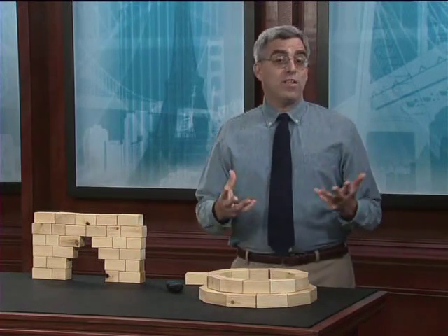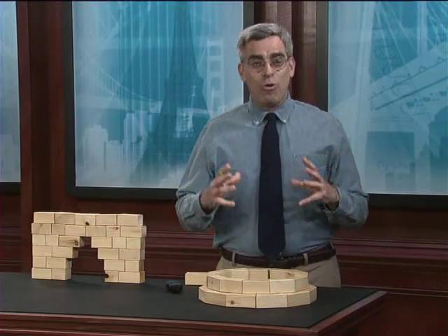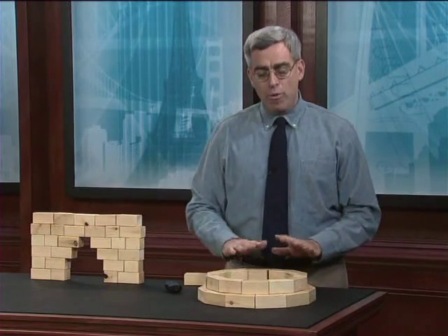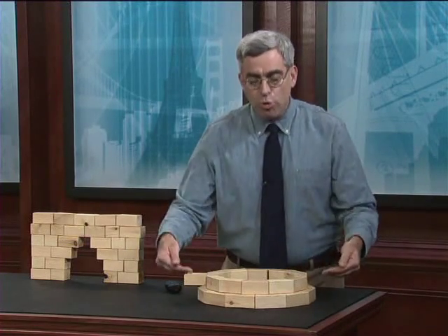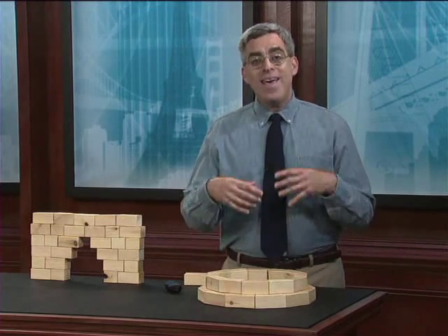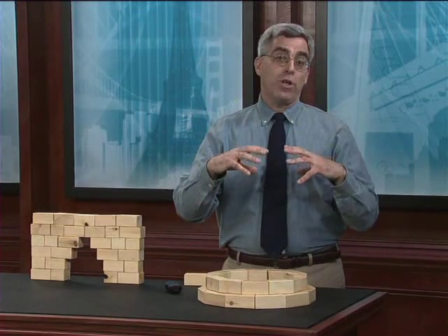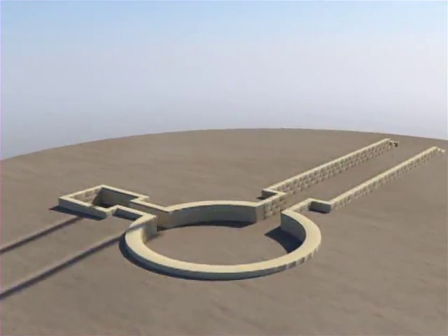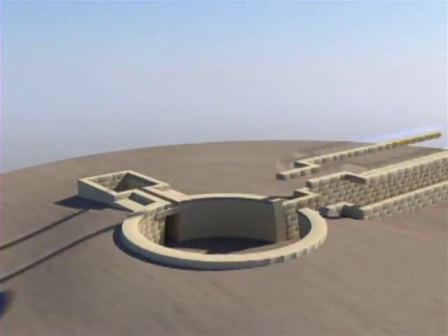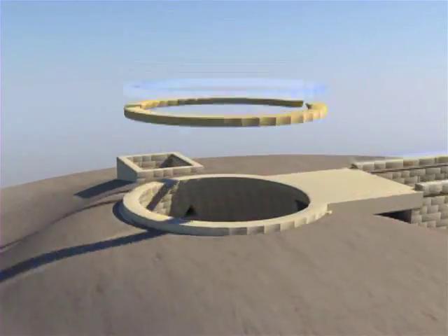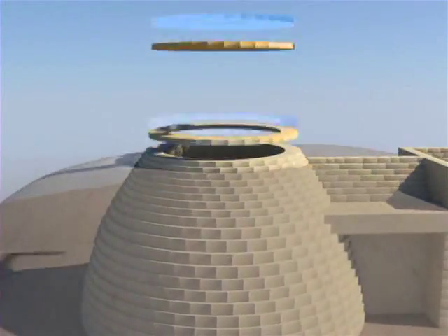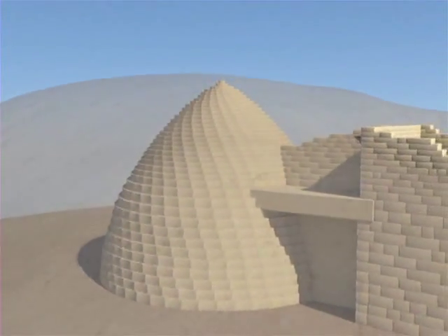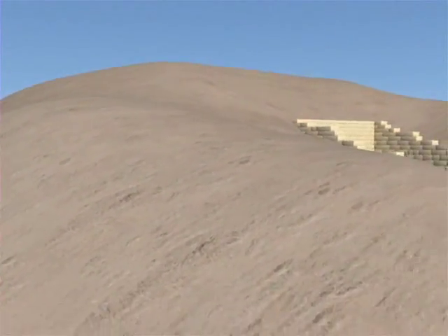And the device that the Mycenaeans came up with was lateral earth pressure. By building a course of stone and then packing earth all the way around it such that the pressure of the earth is pushing inward on the dome to stabilize it, that tendency of the individual stones to fall inward was prevented. And so after each successive course of stone was laid, earth would be packed in up to that level, then a new course could be added, more soil could be packed in to provide that lateral compressive force, and ultimately the entire dome could be constructed, but only if it was built entirely underground.